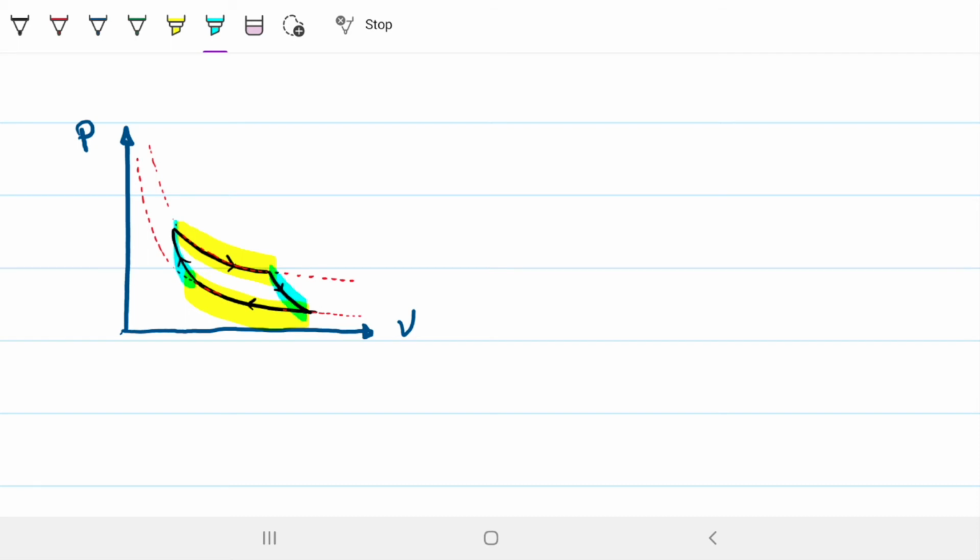Right? The particularity of this problem is that we're given the temperature boundaries, but we're not given one state completely defined, whether this one, or this one. We're only given the pressure of one state and the two temperature boundaries. So that means that we cannot find volume or masses for those states. So we need to find relationships between the things to be able to define the state as best as we can, but we won't be able to completely define them in the sense of finding volumes and masses. This is the tricky part about this problem.